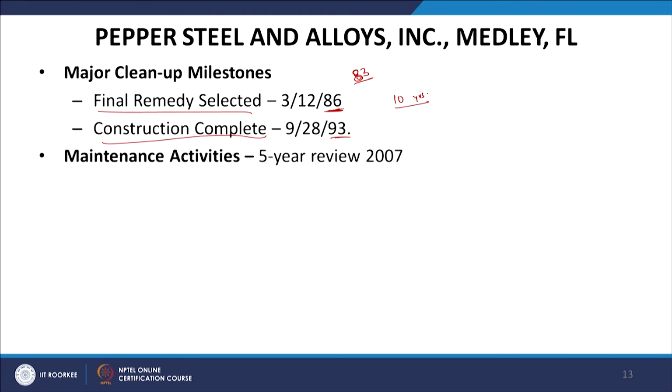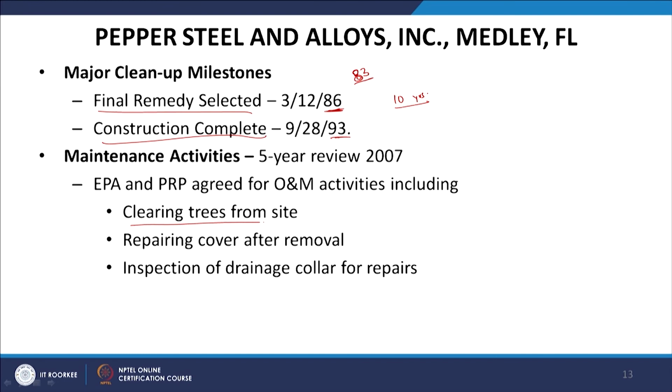Maintenance activities, again, are a critical aspect, including the 5-year reviews. They found trees on the site and the cover was damaged. This is an important aspect: though you have this solidified and stabilized mixture, you want to take the extra precaution of seeing to it that your mixture is not exposed to rainfall or any other sources of water or leachate.